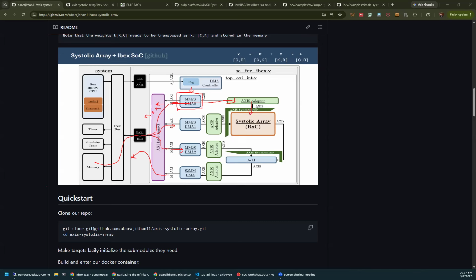And we saw previously that when this AXI stream goes in, we have to synchronize with the other AXI stream, right? Because they both have to go in at the same time. So this stream also has to come before this one goes in. For that to happen, this DMA should also get a chance to request something from the memory, right?